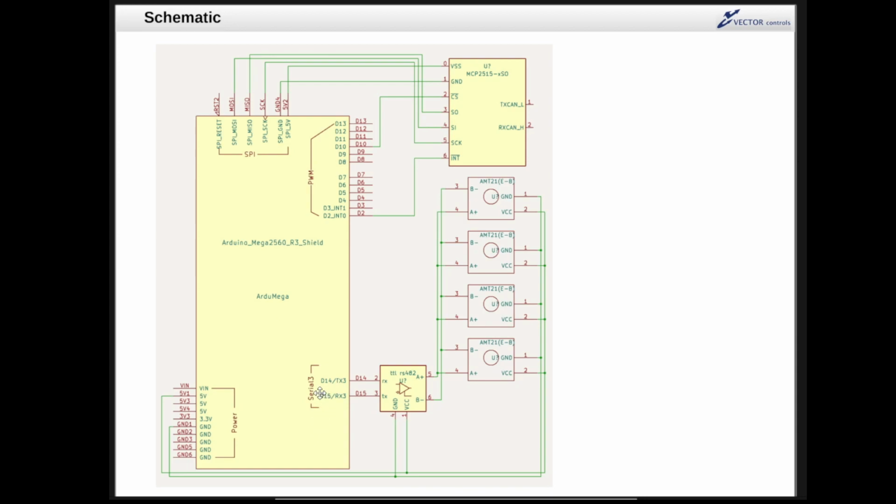So we could technically have each individual serial port connected to an individual RS485 chip and a single sensor. This will definitely reduce it. It's going to take about 4 milliseconds to do the whole thing instead of 8, because I still have to send and receive. For sending and receiving, I would take only 1 millisecond each, 1, 2, 3, 4, and an extra one for writing to CAN. So it'd be like 5 milliseconds altogether.